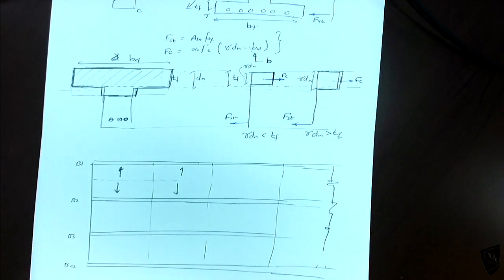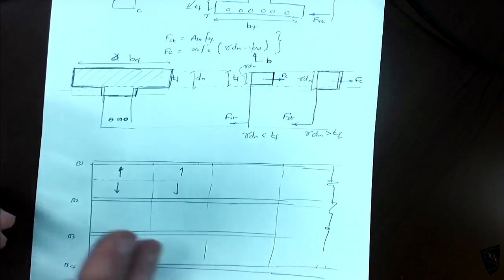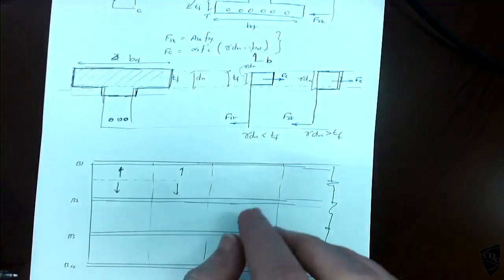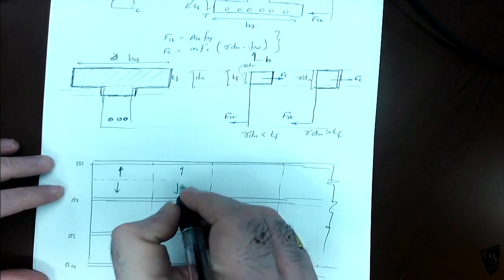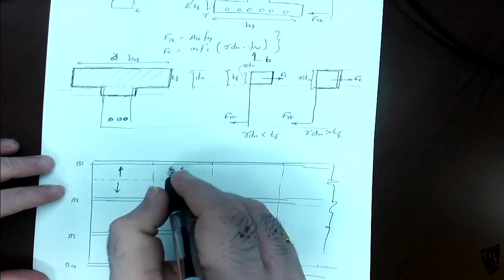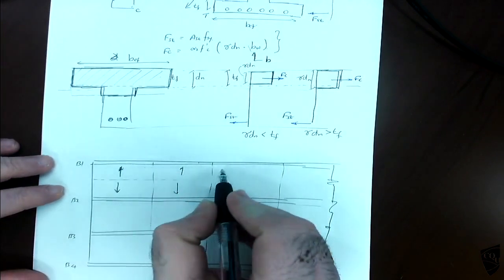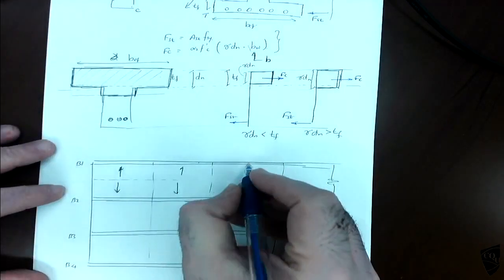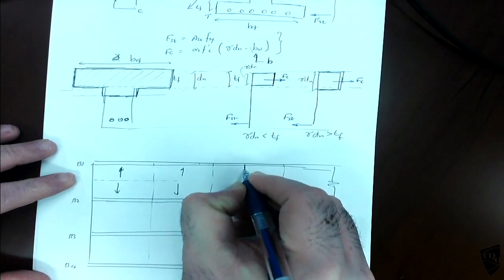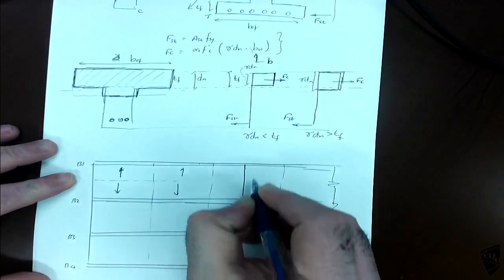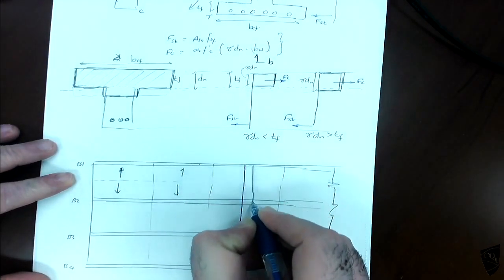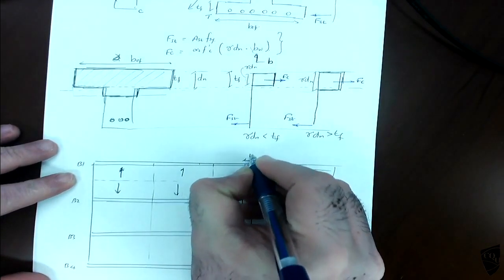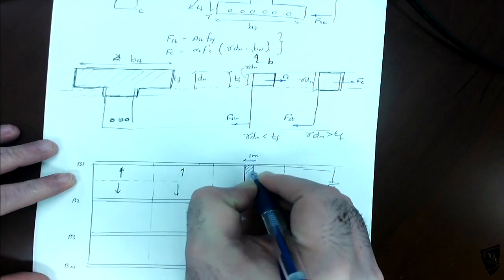So when you design this beam, this will deflect like this. So it will deflect. This is the span, not this one. So when you look at that one, we need to design the slab this way because the deflection will happen. So we will take 1 meter strip, 1 meter strip.